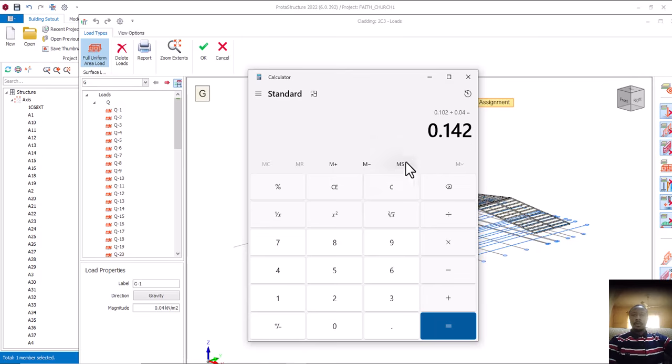So in summary of this, we can start to use 0.15 kilonewton per meter square. Which means that our ceiling board, both the accessory and the ceiling board itself, is going to be 0.15. I'm sorry, I'm coming. Yes, this is the 0.15. This is what we have calculated. So what we are now going to be having is 0.15, which is for the ceiling.